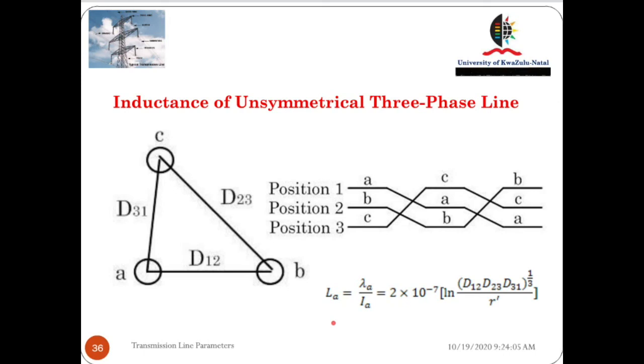They cannot cause unbalanced voltage at the receiving end. So to avoid interference in the communication lines, to avoid unequal inductance, to avoid unequal voltage drop, and hence unbalanced voltage at the receiving end, we do the transposition by changing the position of each of the conductors in cycles or steps.